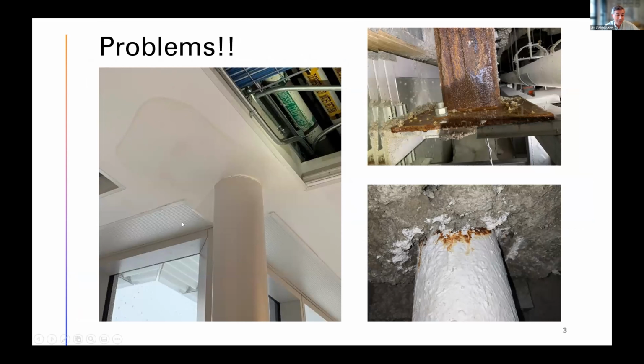When you see water leaking in a building or ceiling, you don't necessarily jump to the conclusion that it's a roof problem. When you've got horrendous, egregious thermal bridging at the spandrel conditions, and it's not just that they got to paint the ceiling every once in a while. On the upper right corner, there's some rusting of the steel, and this is a building that's only a year old. And the upper left, the lower right as well. Thermal bridging can cause structural problems.